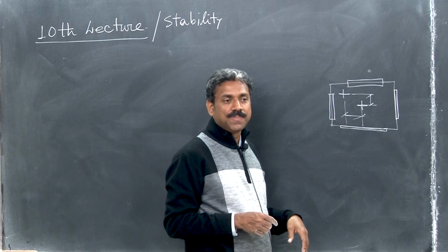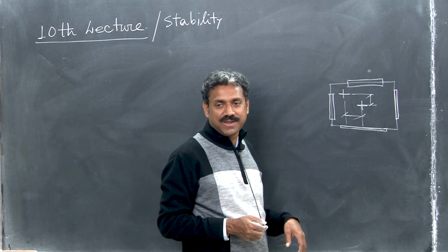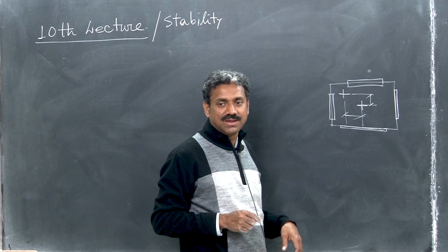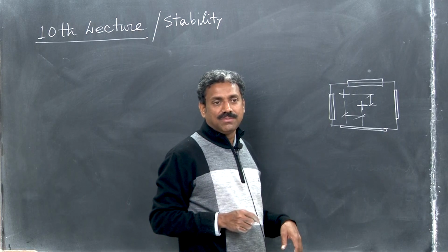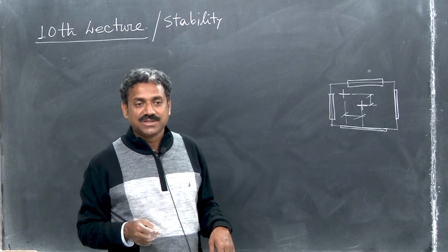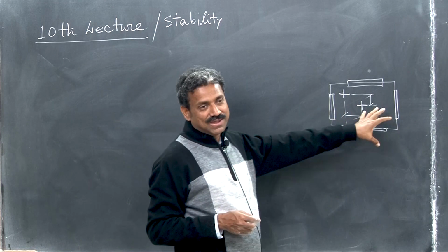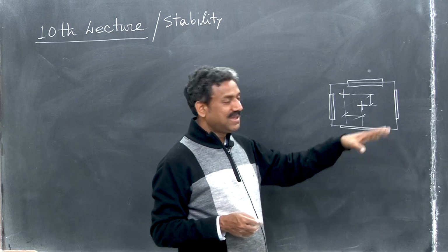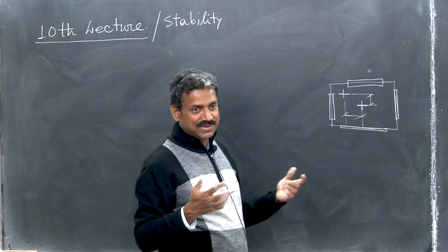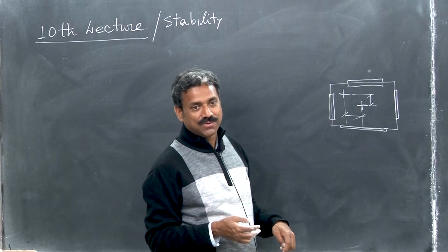You see that. And then always in seismic design, you have to consider some minimum eccentricity, 5% or whatever. There are formulas in the code, IS 1893, to take care of the accidental eccentricity. So things are similar: torsional flexural coupling in buildings in earthquake engineering, and here also torsional flexural, where it is buckling. But the special cases are one axis of symmetry, two axes of symmetry, and things like that.